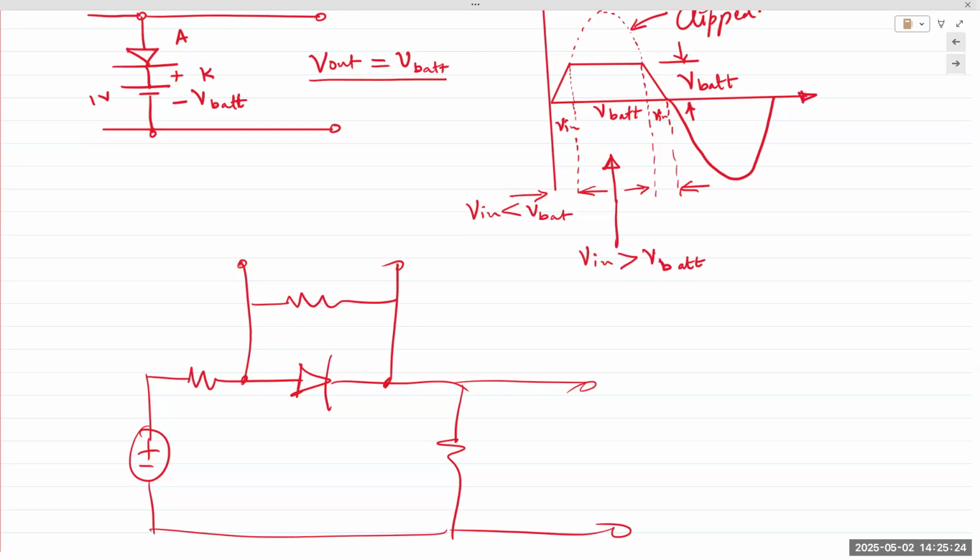We only looked at one other diode: Zener diodes. The Zener diode is going to hold the voltage across itself constant. So if your peak-to-peak voltage is 12 volts, and you connect back-to-back Zener diodes of, let's say, 5 volts, it's going to start conducting and would not permit anything more than 5 volts to reach the output. So it clips the top of that waveform.